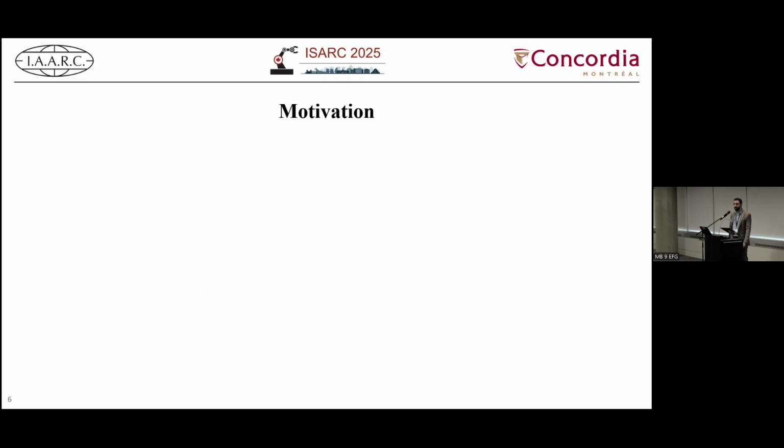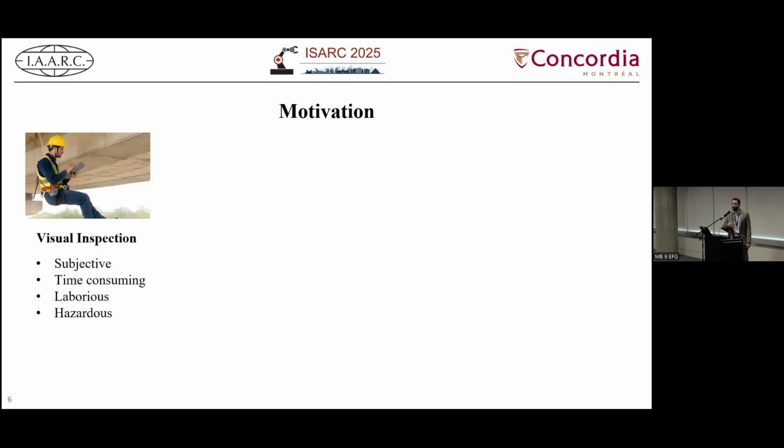Now, why am I talking about condition assessment of bridges and specifically about cracks in bridges? Because there are different ways of doing this. Previously, and it's still the most dominant approach, people relied on visual inspection. You would dispatch a maintenance team that would visually inspect the bridge of interest, and they have to report what they come up with. The problem with this approach is that it is subjective. Obviously, it is time-consuming and very labor-intensive, and in many cases it is hazardous, specifically when you require the personnel to reach some tight or very high spaces.